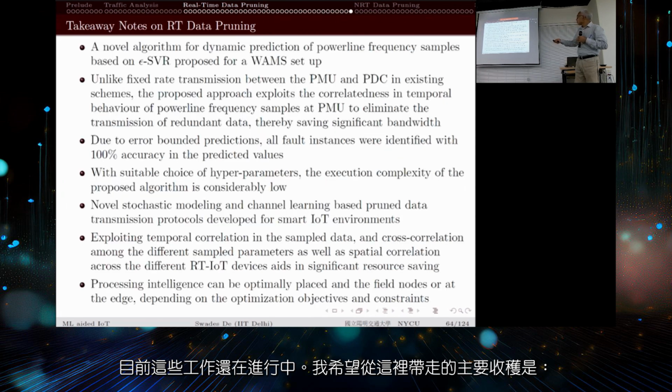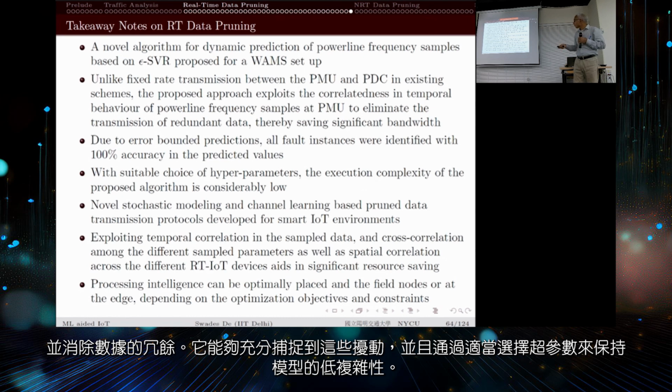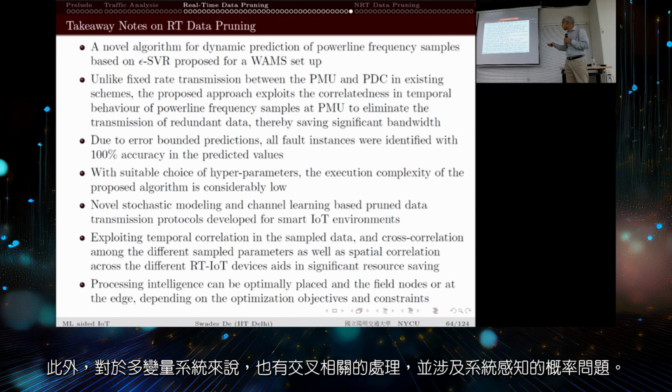Okay, so the major takeaway that I would like to carry from here is dynamic prediction for single variate. Unlike fixed rate transmission between PMU and PDC, the proposed approach exploits correlatedness and temporal behavior of the power line frequency, to eliminate the redundancy of the data, and it has been able to capture these disturbances sufficiently with a suitable choice of hyperparameters.